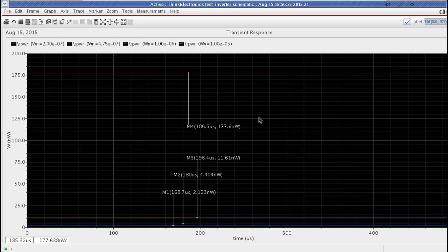It is clear from the simulation that the value of static power depends mostly on the width of NMOS at 0 gate voltage, and it increases proportionally with the increase of Wn.